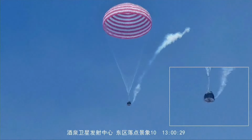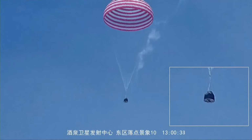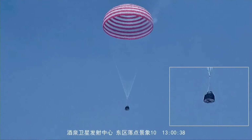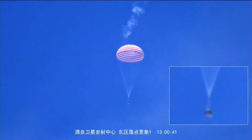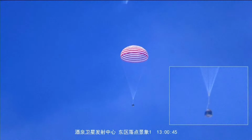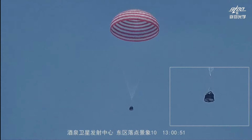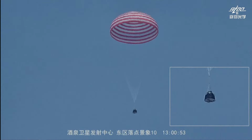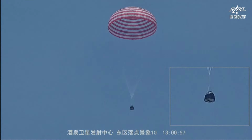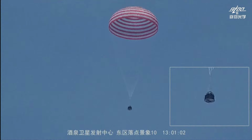Yeah, because it's for safety precaution. It's toxic, but it's necessary. You see that, as I mentioned, it is a controlled re-entry. As Professor Zhang mentioned, we can control the attitude of the capsule during the re-entry. This is the function of the propulsion system on board the re-entry capsule, but it only changes the direction in the roll direction, to change the direction of the lift. With the change of the lift, we can change the trajectory to the landing point.